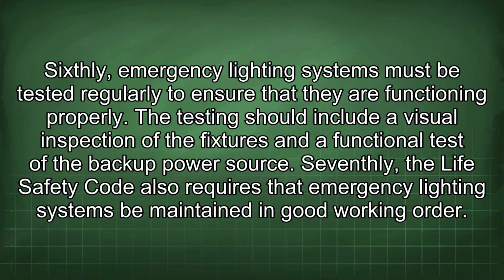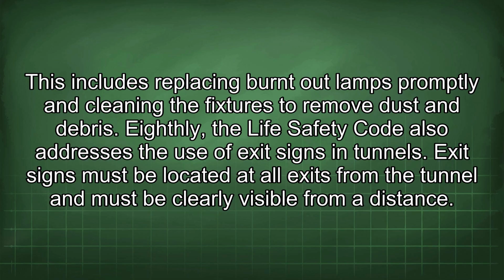The testing should include a visual inspection of the fixtures and a functional test of the backup power source. Seventhly, the Life Safety Code also requires that emergency lighting systems be maintained in good working order. This includes replacing burnt-out lamps promptly and cleaning the fixtures to remove dust and debris.